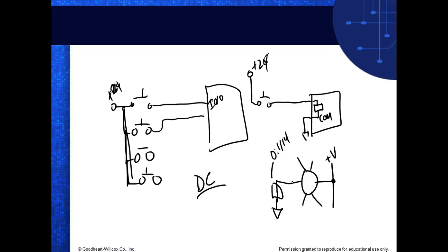And I don't have an option on what I use for the common for the inputs because it is a sinking module. I think the output is sourcing on the 504. So if you're on the 504s, just look at those modules. We have a 16-bit input module, and we have a 16-bit output module, I think, on most of it.